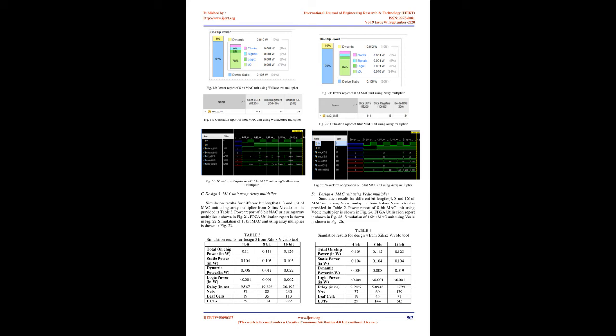2. Wallace tree multiplier. It is an efficient hardware circuit designed to achieve higher speeds of operation. It was designed by Chris Wallace in 1964. It is a variant of the long multiplication method. The Wallace tree reduces the number of partial products and uses a carry select adder for the addition of partial products. Here, the total delay incurred is proportional to the logarithm of the length of the multiplier operand. This in turn results in faster computations.